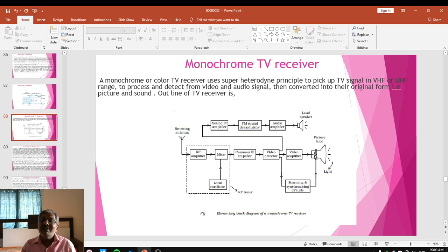It is passed through the control grid that controls the flow of electrons and passes it to the pre-accelerating anode, where the electron beam is accelerated. Then it is passed to the focusing anode, where somewhat scattered electrons exist.